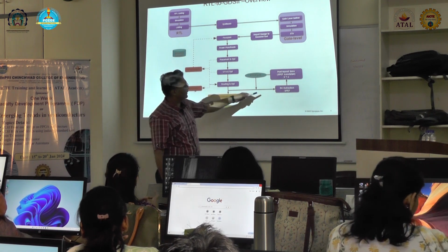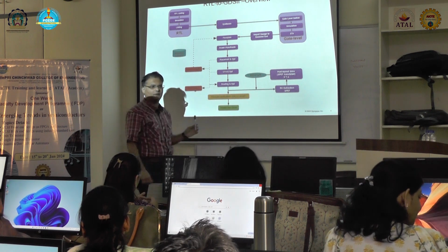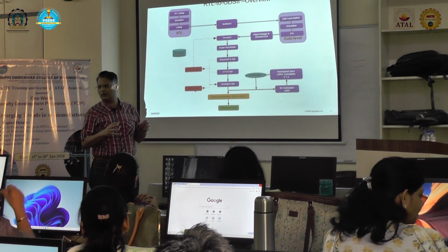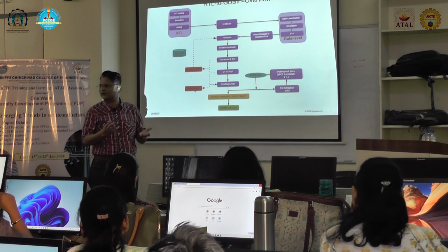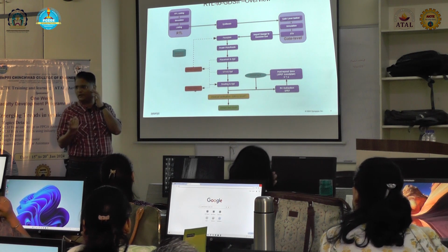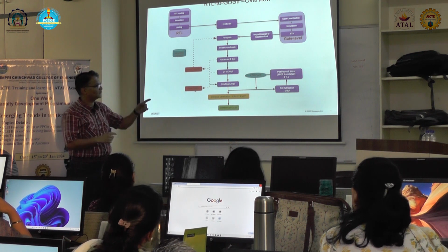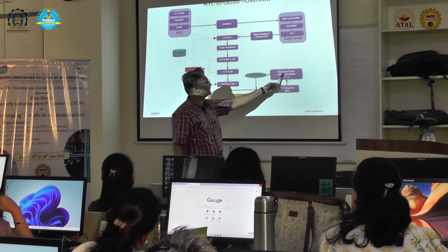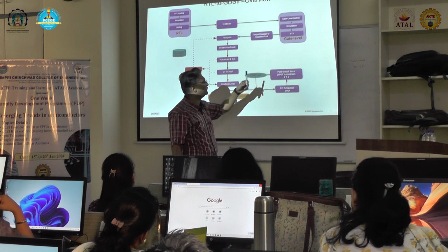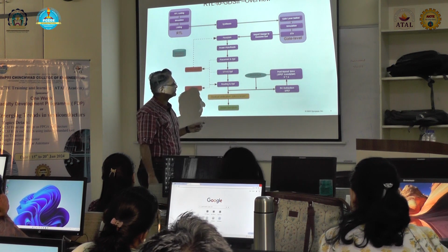So again, this output netlist is simulated using the same test to check whether it matches the functionality, whether it is doing what it should, or whether backend has done something wrong. If backend has done something wrong, then that test will not operate. It will fail. So the same thing is being done again in the post-layout simulation. We do the post-layout simulation and we again confirm that the circuit is working fine.